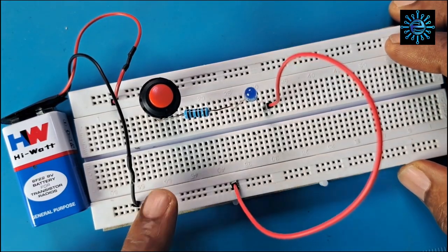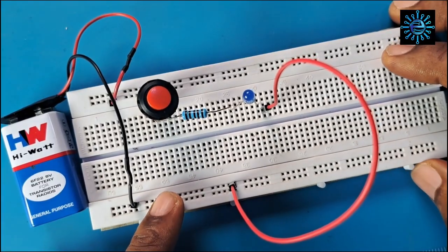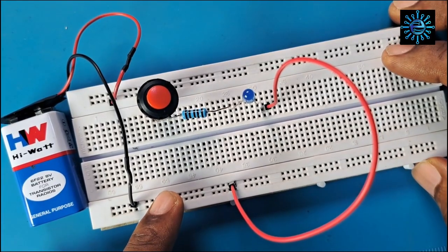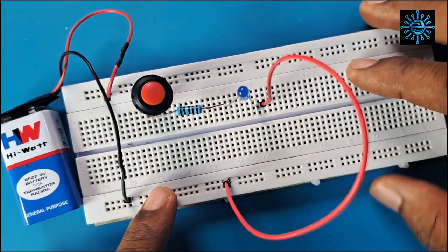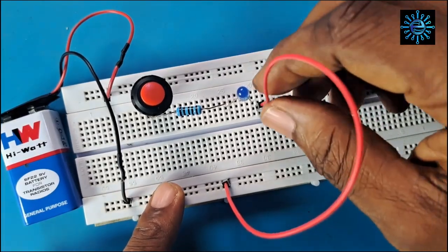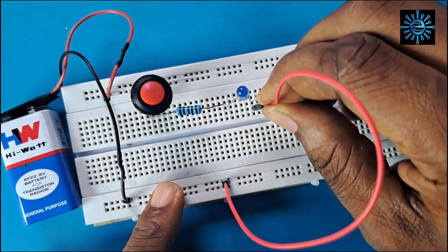So when you make your circuit and you discover that it is not working as expected, you will go ahead and troubleshoot it. And one of the things you can do is to check if the component legs are inserted in the correct holes. So to fix this kind of problem now, what I would do is to move this jumper wire here and put it here.